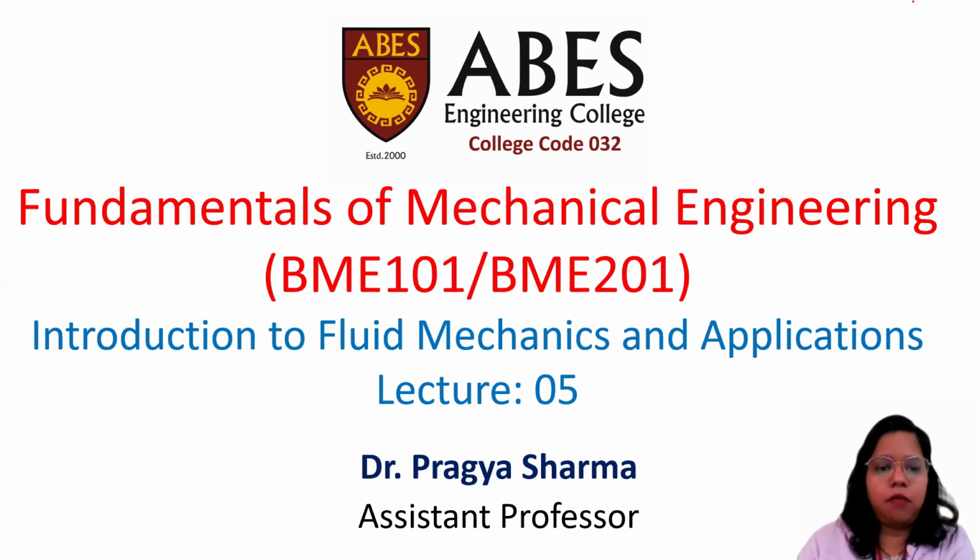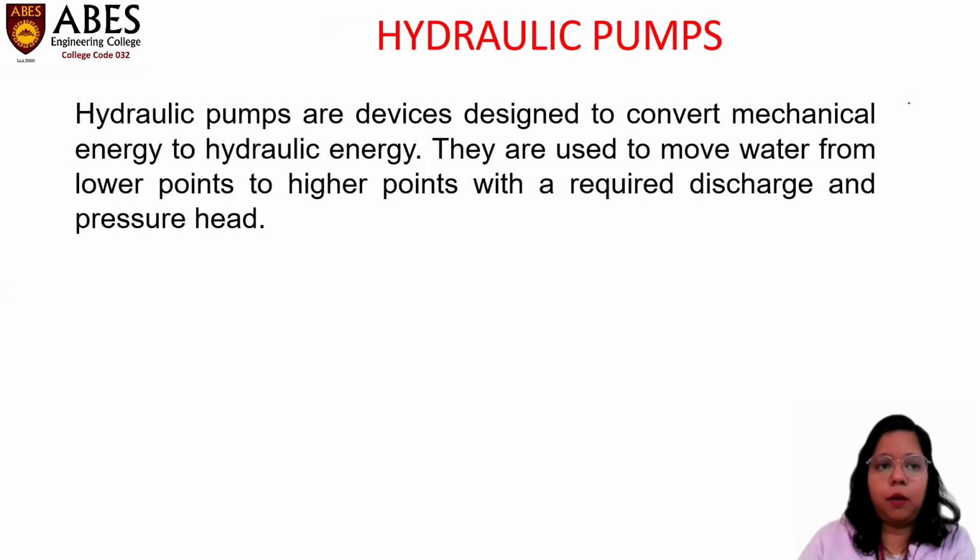We have covered a few topics in previous lectures. So, now the topic we are covering in this lecture is hydraulic pumps. What are hydraulic pumps? These are devices basically designed to convert mechanical energy into hydraulic energy. They are used to move water from lower points to higher points with the required discharge and pressure head. We have generally seen pumps installed at our homes to get water from lower points to higher points with the required discharge and pressure heads.